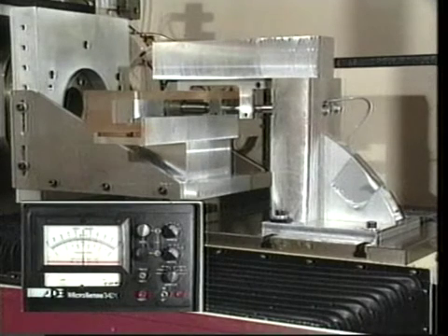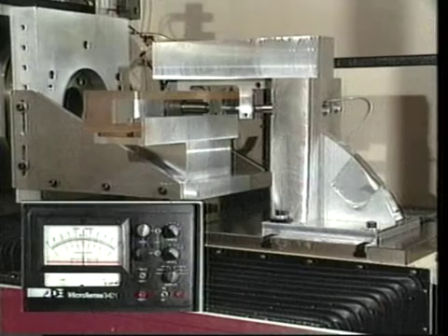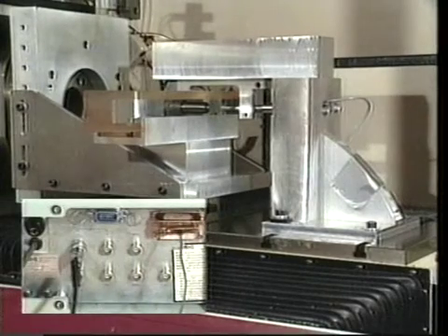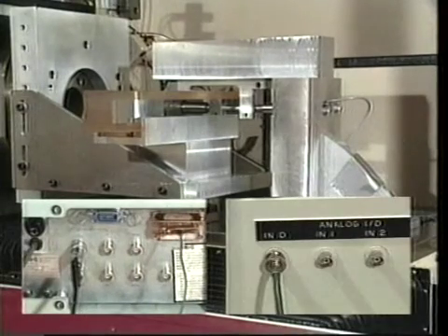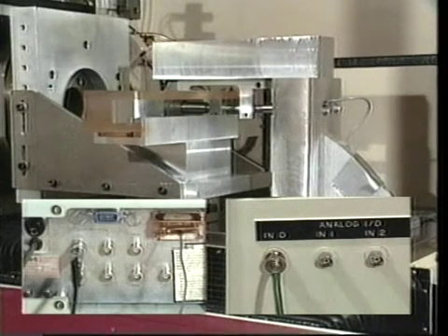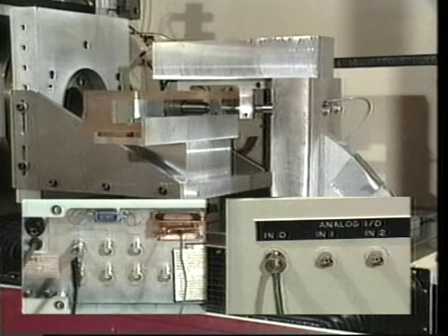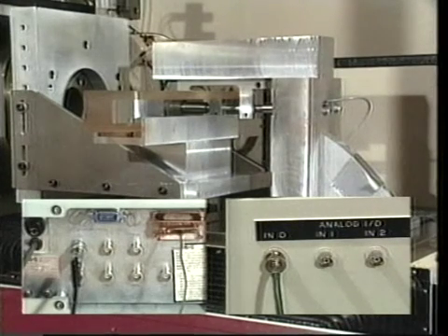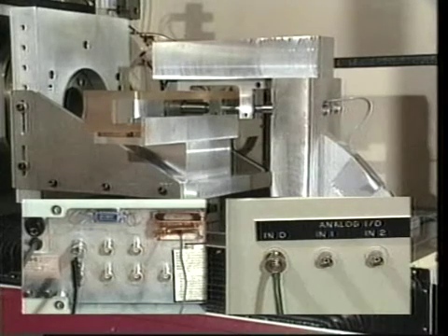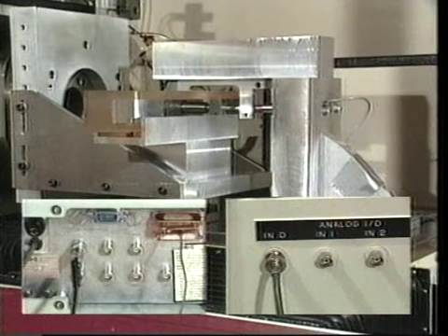The analog voltage signal from the capacitance gauge will be sent to an analog input on the DTM controller. Inside the DTM controller, the analog signal will be converted to digital values. The DTM controller, which has resident data gathering routines, will record the x-axis positions and their respective digital voltages. Later, these voltage levels will be converted to distances with the 2.5 micrometer scaling factor.